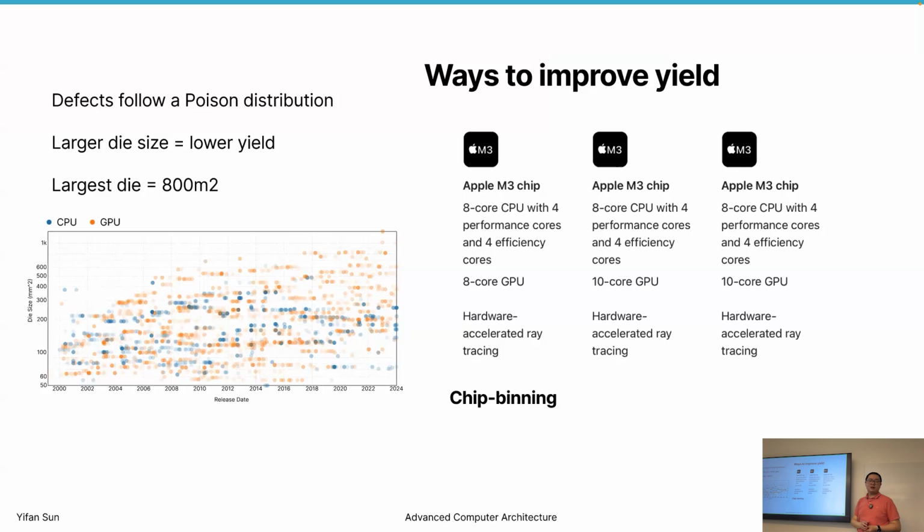You buy a chip, and not all the chips are the same. They are this different and that different, right? So even if you see 10 cores, perhaps what they actually have is 12 cores. When you say 2 megabytes of cache, they probably build 2.4 megabytes of cache just for redundancy, so that they can sell a reasonable device. Okay, this thing is called chip binning.